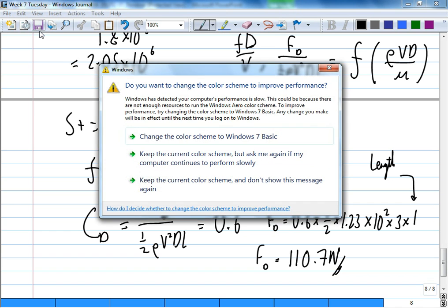So in this case, because the controlling one is the waves, and I told you the wave restoring force is the Froude number, the wave controlling parameter is the Froude number. So here there's the Froude number, and the drag coefficient, for the wave drag anyway, which is the main component. If your boat is a conventional design, the drag curve is like this, it's higher.